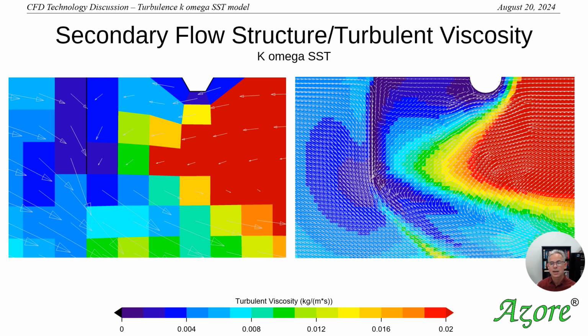So this is a good example of how the mesh itself plays a role hand in hand with the turbulent viscosity itself to try to capture the effects of turbulence in this area for the mesh length scale that you might select for the problem that you're solving.